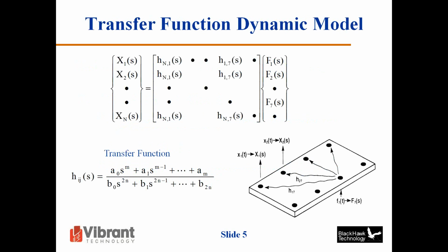Okay, here's what we call a transfer function model. Now, this is a more general purpose model, and we use the word transfer function, and we think of a structure as a black box that has so many inputs applied to it, and then the transfer functions multiplied by the Laplace transforms of the inputs gives us Laplace transforms of the output.